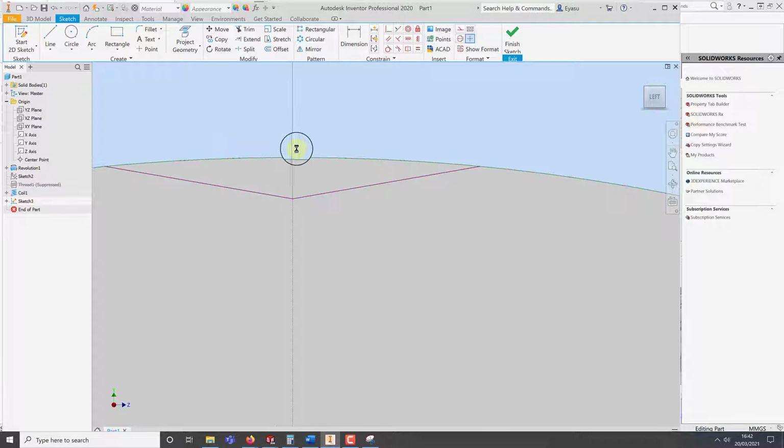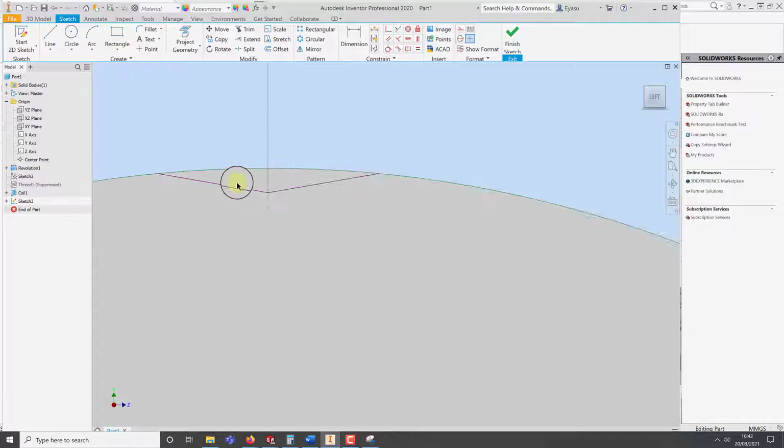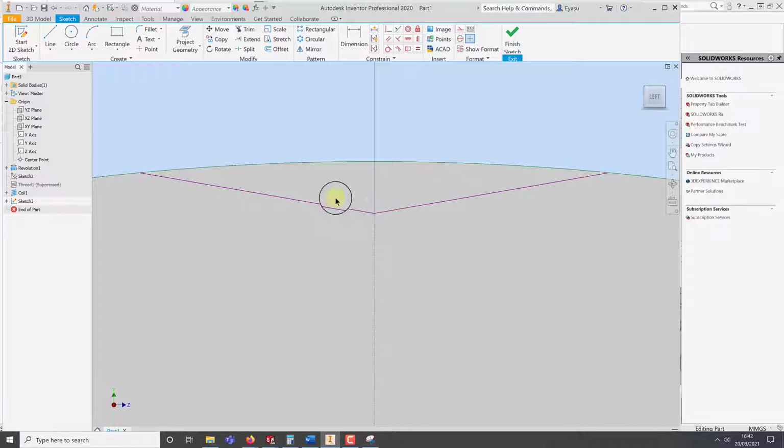And what you need to do now, you would decide, maybe you might say, okay, I want this to be some sort of shape. Sorry. So you write the size, and I need to mirror this actually. So I'll click onto the green dot to the green dot. Make this line into a construction line. Then I'm going to go to mirror, select these two lines. Oops, sorry, not included in this.